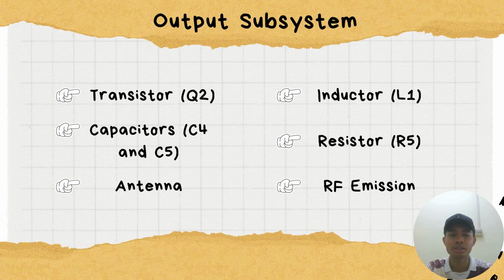Next, capacitors C4 and C5. A component of the matching and tuning network are these capacitors. L1 and C4 work together to determine the oscillator's frequency. Most likely, C5 is a coupling capacitor that only permits the AC modulated signal to get through while preventing DC from getting to the antenna. Additionally, it collaborates with L1 to match the antenna's impedance to the rest of the circuit, a necessary step for effective energy transfer.